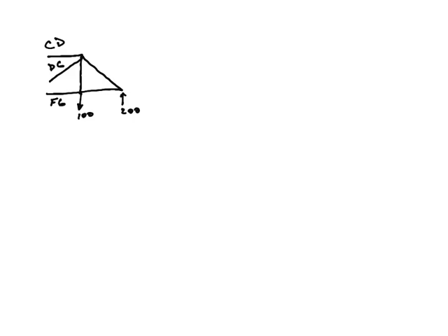Now, unlike with method of joints, where we would try to logically figure out what we think the direction should be, here, don't worry about it. Just always guess. We think the forces will always be in tension. So I'm just going to assume all of these 3 unknown members are all in tension. And if I get a negative answer, then I know, oh, it was actually compression.